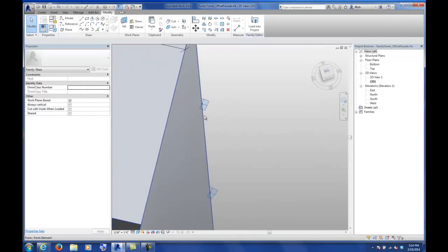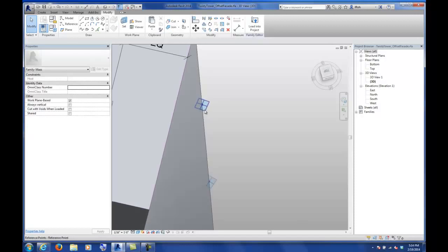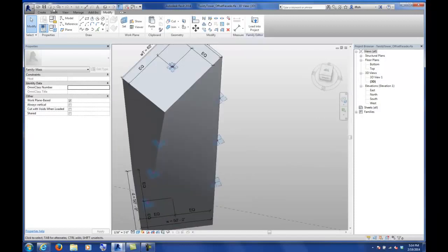Jeremy, yes. Can I ask a little bit about the normalized curve parameter? I'm not familiar with it in Revit, but sometimes in Rhino when you get the U coordinates for the curve, you'll end up with spacing really far apart and really close together for the curvature. Does the normalized average it over the entire length of the curve?